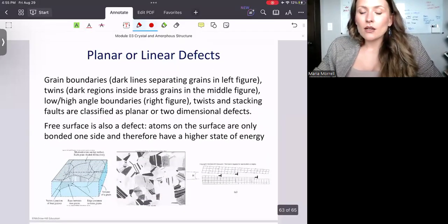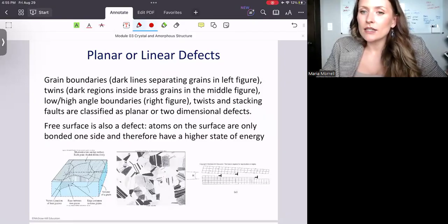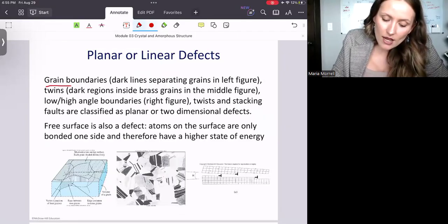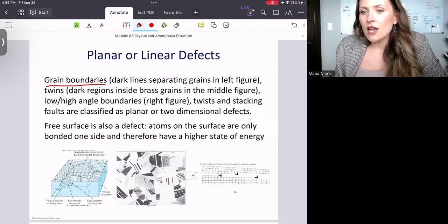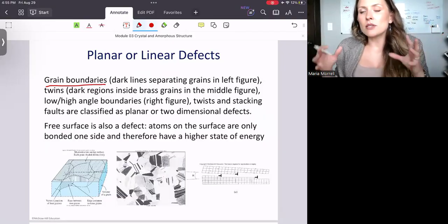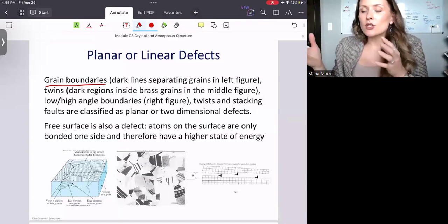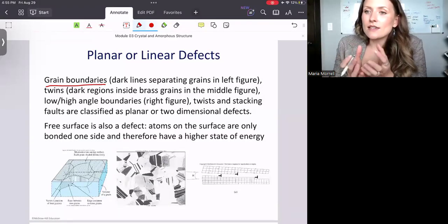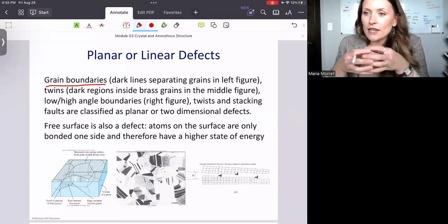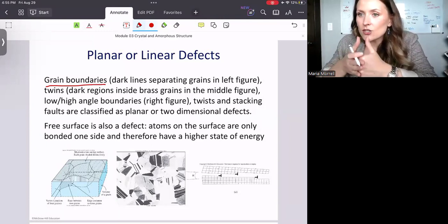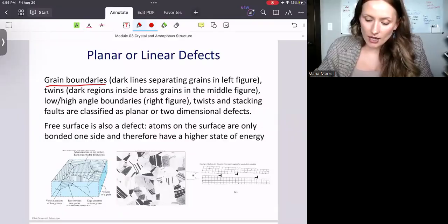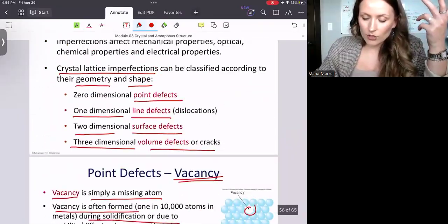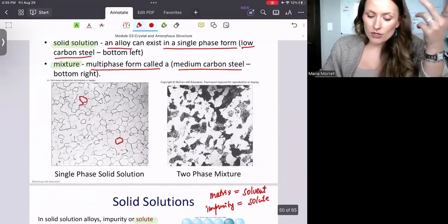Now, a little bit more on planar defects, and specifically the grain boundaries. I already mentioned them a little bit today, and it's easy to understand. Whenever you have a liquefied material that you now solidify, you have these grains that grow. They nucleate and then they grow in size, and eventually they basically touch each other. And so usually you are able to see that as a grain boundary. Perhaps the best example is something that I've already shown you when I was showing you the alloys. Yeah, right in here.